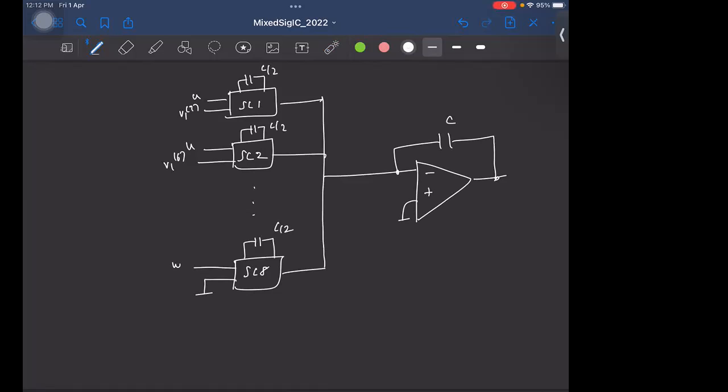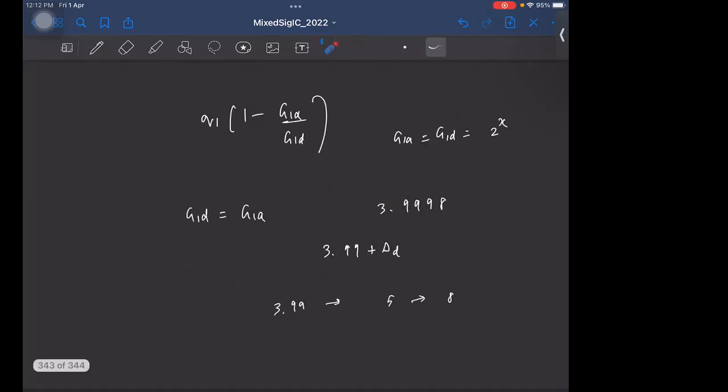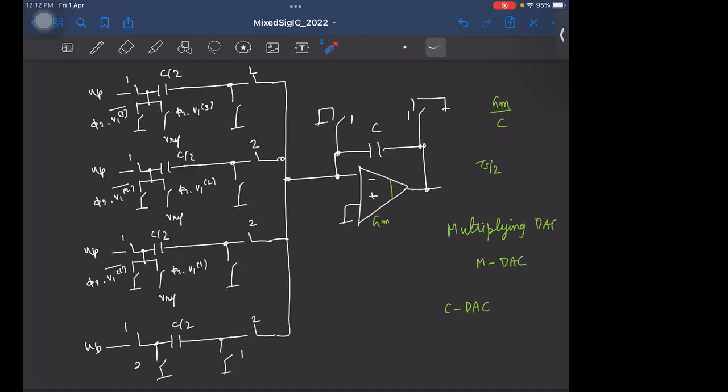So now that we know how this residue amplifier is realized along with the DAC, let's look at the circuit once again and try to see where all the error in the gain can come from, right? So remember, overall we wanted a gain of 2 in this case, and each branch has to realize a gain of half, right? But what do you think can go wrong in this procedure? Yeah. Correct.